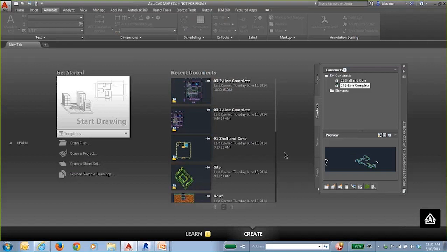Now I have a couple of notes here. Other users have read-only access. They can view the last saved versions while the changes are being made. So again, while you're making changes to the file, you're not going to allow anybody else to be able to make changes or even use the one that you're working with. The changes that you make aren't visible to others. And also, as the checkout file is saved, no XREF reload notification is sent to others. So that gives the rest of the team the ability to work on the files that they have to work on without having to worry about what you're doing at the moment and trying to keep up with changes that might be taking place.